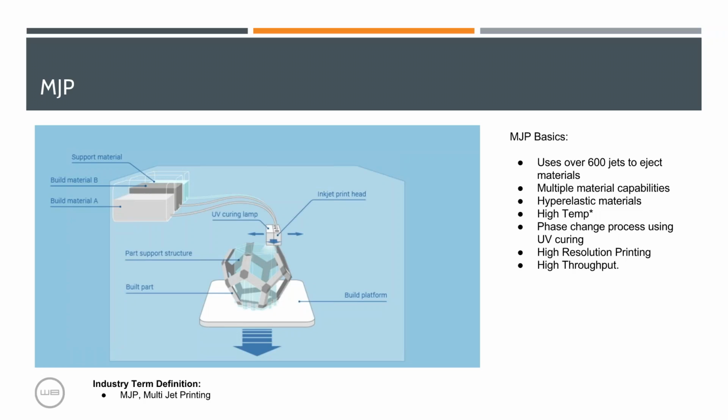So how does this work? There are 2 different types of movements in these printers. With our ProJet 3600 line, the build plate is the one that moves back and forth laterally, in the X direction, and the print head moves in the Z direction. So the part moves back and forth underneath the print head. It prints in some cases 2 materials, in other cases multiple materials, and you can actually mix them at the same time.